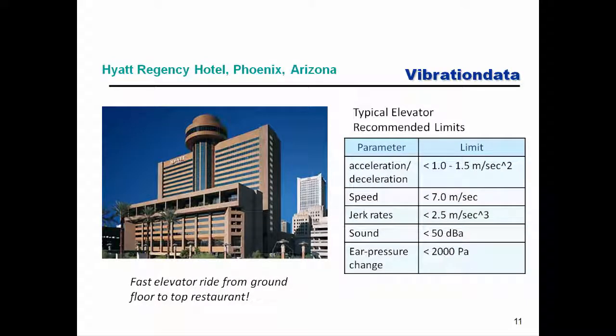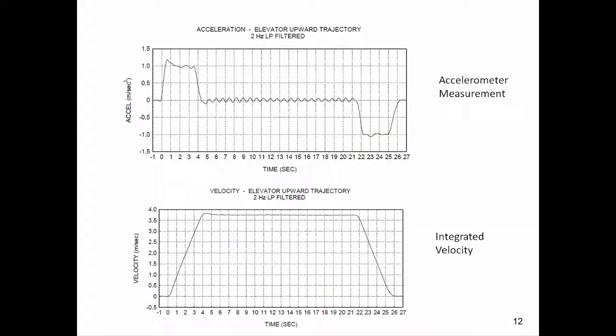So what I actually did, about 10 years ago, is I had a laptop computer with a little student-variety data acquisition system and an accelerometer, and I went and actually measured the elevator vibration for a straight non-stop ride from the ground floor up to that revolving restaurant. On the top here you can see the acceleration, and I've made a note that I applied a 2 Hz low-pass filter on this data to filter out some high-frequency noise.